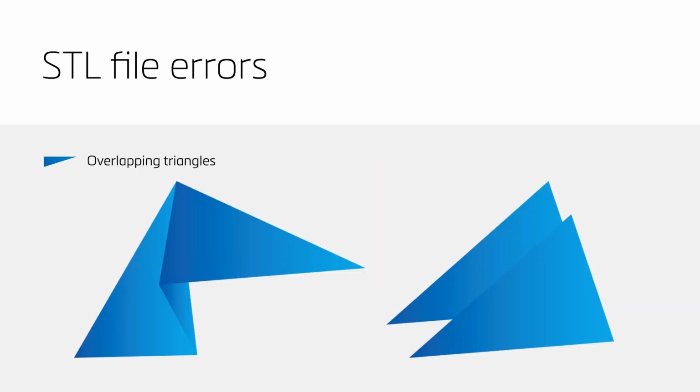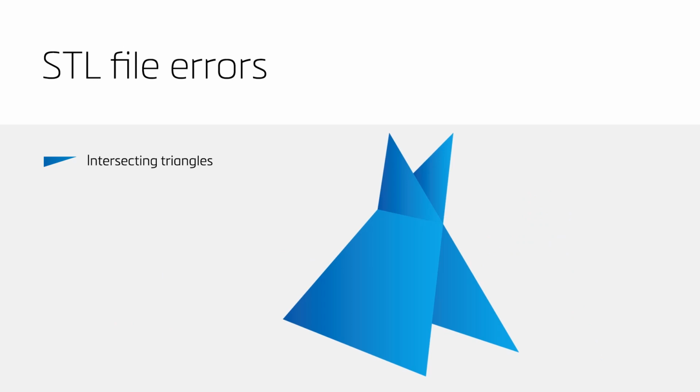The fourth error is overlapping triangle. Triangles are overlapping if the distance or angle between them is smaller than a given tolerance value. These triangles can often be recognized as a zigzag form in the surface, likely to be less crucial for printability, but we recommend to remove them anyway, since these fixes will improve the surface quality. A last error, which we will discuss, is intersecting triangles. You usually will have these triangles if you have intersecting shells. Triangles that intersect need to be unified.